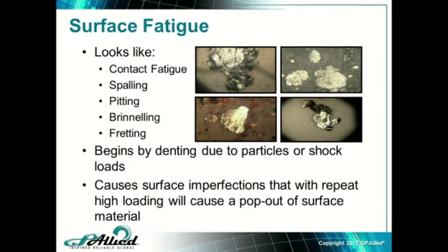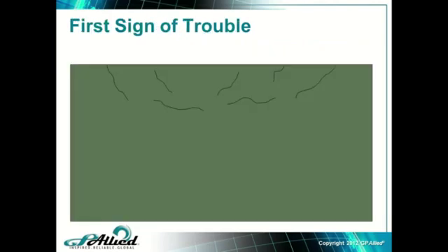And of course, once it begins, it accelerates very, very quickly. So we've got to ask ourselves then, where's our first sign of trouble? Well, our first sign of trouble is this subsurface fatigue. Now, a lot of people ask me, can oil analysis find subsurface fatigue?